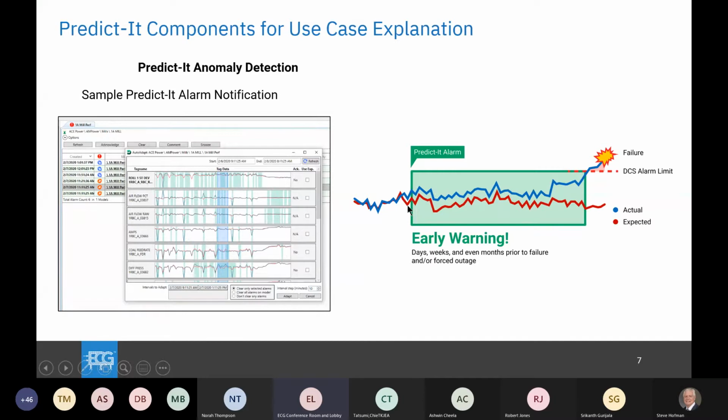What we're looking to see is that the blue line is over top the expected value. And the expected value is generated based on its relationship to the other sensors in the operating state that that asset is in. Let's say 10% load versus 50% load. And so once you have these expected values, you can then start measuring statistically how different it is, and then alarming these anomalies. And these are things that an operator just does not have the accuracy to be able to detect because it's so subtle. But it is an accelerated aging event taking place that's going to take life off their rebuild cycle.